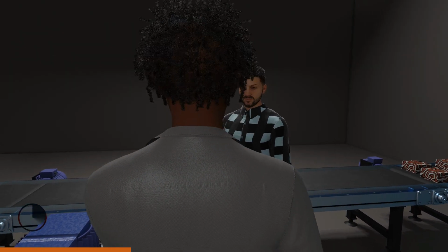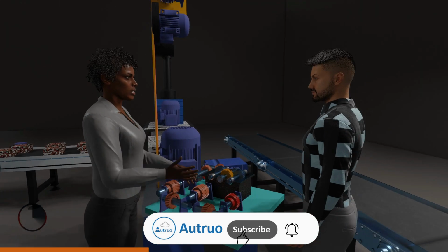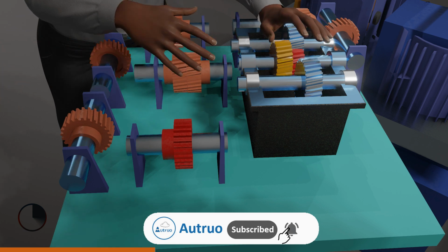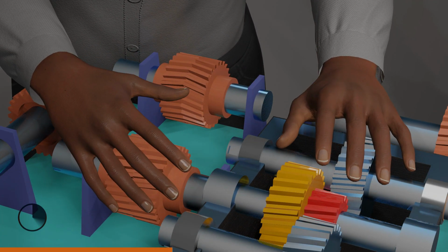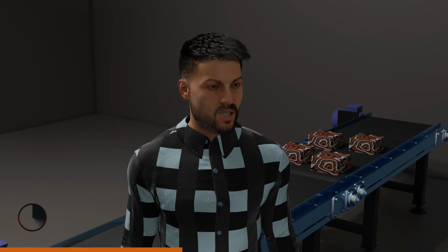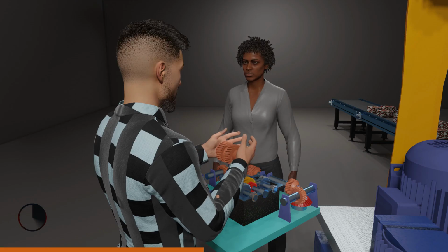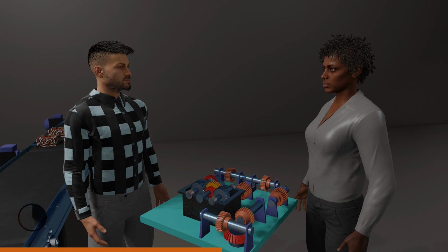Double helical gears, on the other hand, can also be known as herringbone gears. This gear consists of two teeth designs which can be in the same direction or opposite directions. And it is based on this design that the double helical gear was primarily designed to overcome the disadvantages of the high end thrust that occurs with single helical gears. To look at it in layman's terms, when two helical gears of opposite-handed teeth are brought together, the end product is what is known as double helical gears, or herringbone gears.